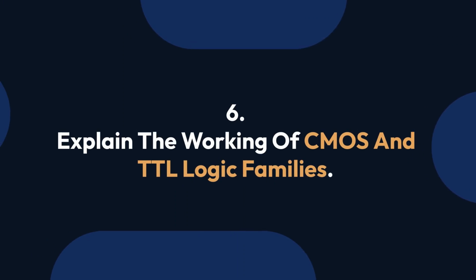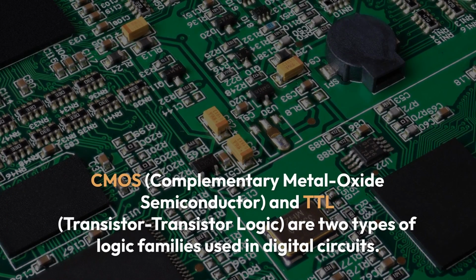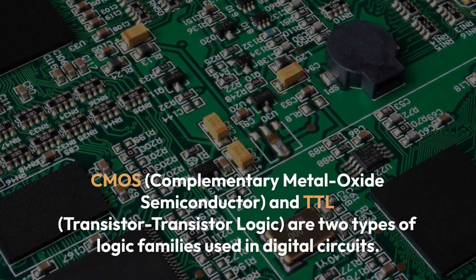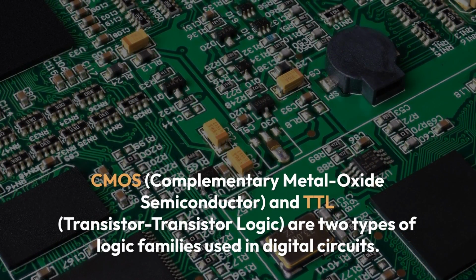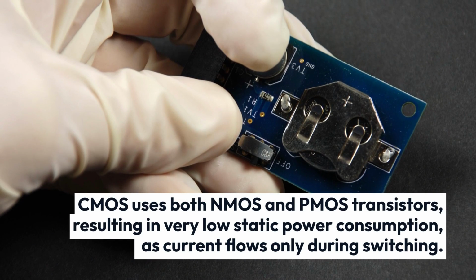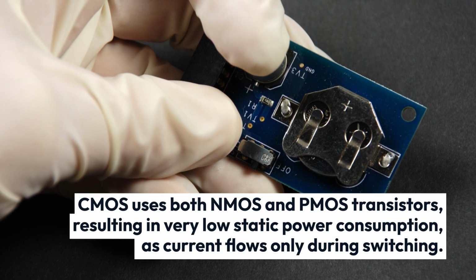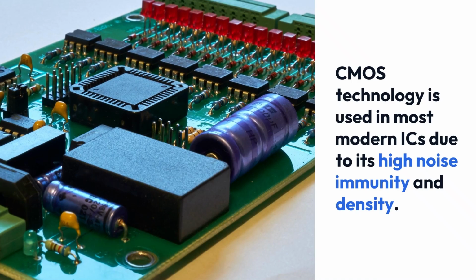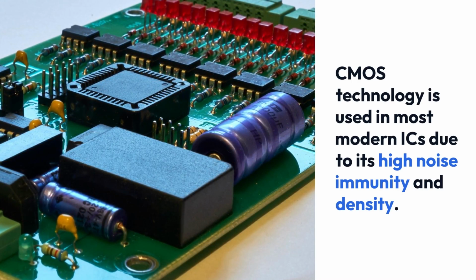6. Explain the working of CMOS and TTL logic families. CMOS, complementary metal oxide semiconductor, and TTL, transistor-transistor logic, are two types of logic families used in digital circuits. CMOS uses both NMOS and PMOS transistors, resulting in very low static power consumption, as current flows only during switching. CMOS technology is used in most modern ICs due to its high noise immunity and density.